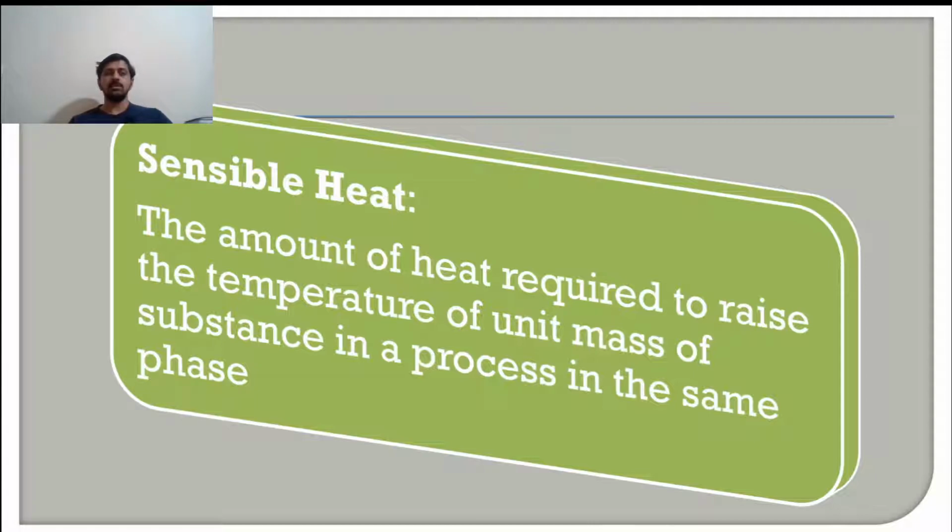Now coming to another important term in the phase change process, sensible heat. That is the amount of heat required to raise the temperature of a unit mass of a substance in a process in the same phase. Suppose you want to raise the temperature of water by heating from room temperature, say 27 degrees Celsius, to 50 degrees Celsius. The amount of heat required for that temperature change, delta T, is termed sensible heat.